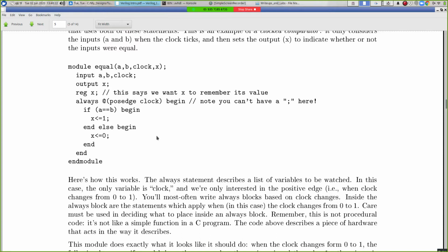And sometimes you'll write Verilog and you'll try to compile it and it'll say this can't be synthesized. And it means you've described a circuit that's physically impossible to build. That's a good point to step back and think about, what does this circuit describe? And this is quirky. This takes more than a couple of weeks to get used to. But we only have a couple of weeks. So I want you to stick with it.